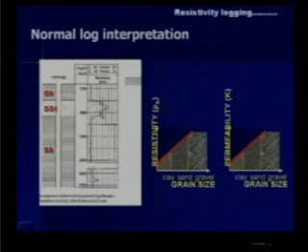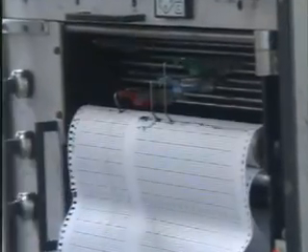If you use this, we will be getting a log something like this. What does it indicate? This is the depth of the borehole. We will be lowering the sonde through the borehole slowly. The sonde will get us digital data between depth versus resistivity. So, this is the resistivity, and this indicates the depth of the borehole. Here it is 1700 feet, here it is 6700 feet from the ground surface.